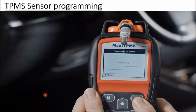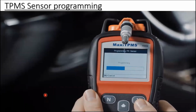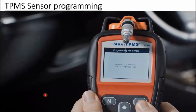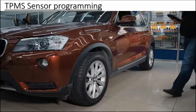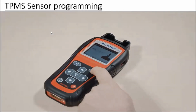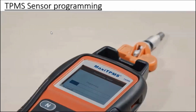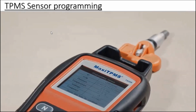Copy by OBD, when available, is highly recommended as an efficient sensor programming method. No relearn is necessary when the MX sensor is put in the same replaced sensor position. Copy by activation. Place the TS508 near the original sensor to trigger and acquire the sensor ID. Place a new MX sensor near the top of the TS508 and press Y to start programming. The original sensor ID will be copied into the new MX sensor.